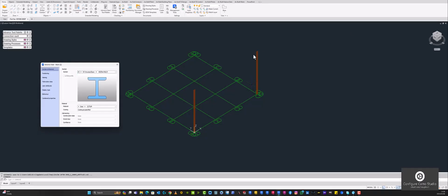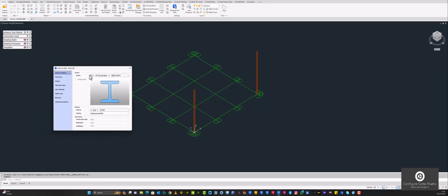All right, so let's go back to Advance Steel. So we go to this area here. The first drop-down arrow shows you the profiles that you have. As you can see, you've got flat bars, angle irons, Kingspan products, round bar, square, and all that. Then the second drop-down arrow gives you the environment. So first of all, the product, the steel section profile, and then now the environment.